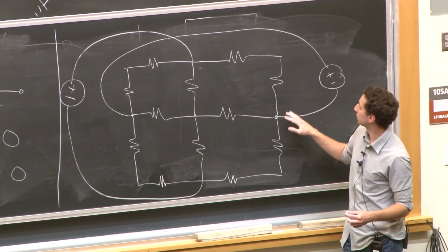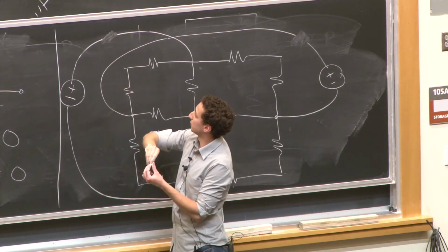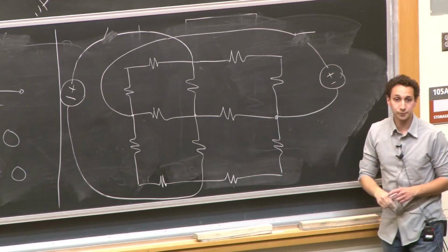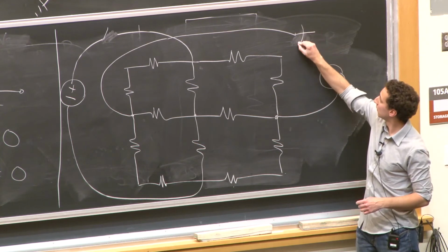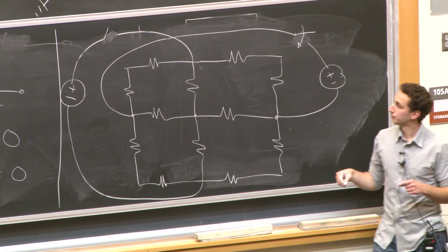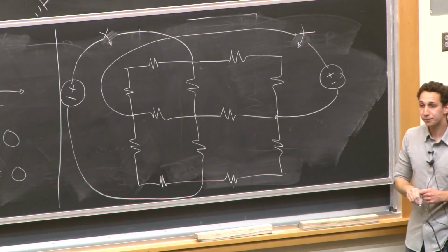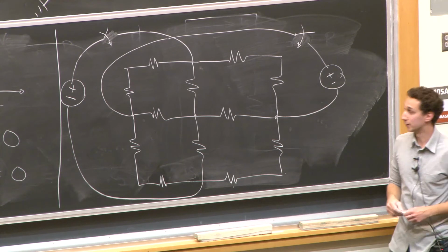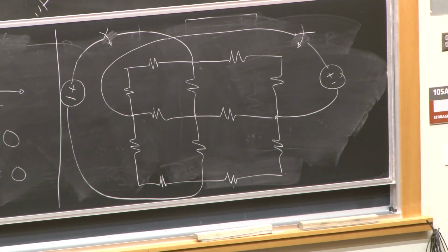So now what we want to do is put in series with these voltage sources a couple of switches. Right, that way, when this one is short, I can make my X dimension measurement. And when this one is short, I can make my Y dimension measurement. Okay? And that's how we can make a two-dimensional touchscreen. And you guys are actually going to build this exact circuit in the lab, and it's actually a pretty fun lab. You get to solder as well.